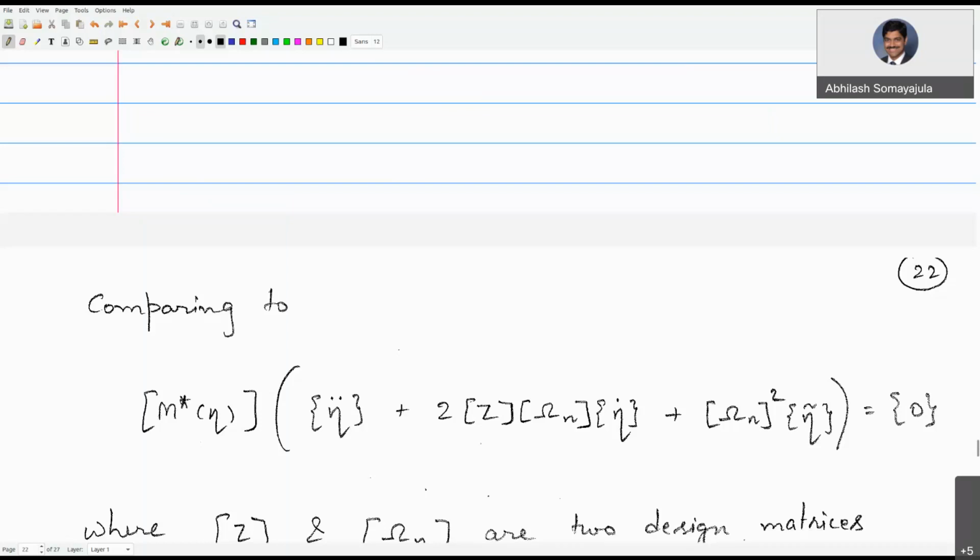So there what they will do, my suspicion is, is have multiple loop closures like the ones we discussed. They'll not be limited to 2 loop closures, but will have multiple rounds of closures in between in order to make sure that they can stabilize the system in some way. But it is quite an interesting problem. In fact, even just looking at quad rotor dynamics is not quite straightforward. It's quite complex in itself because it's a highly underactuated system. You have 6 degrees of freedom to control and you have only 4 rotors, right? So it can be quite challenging to look at.